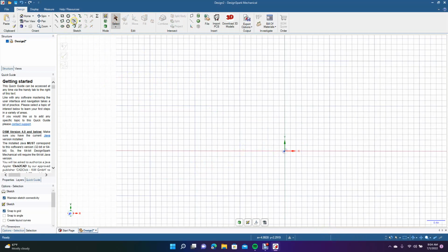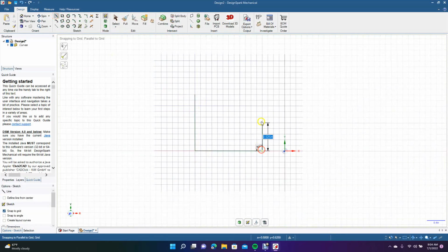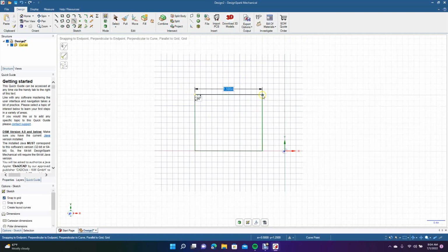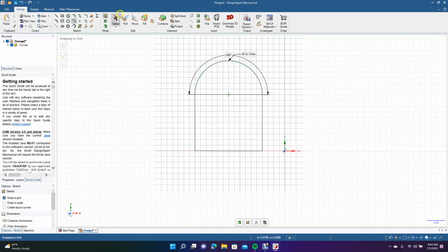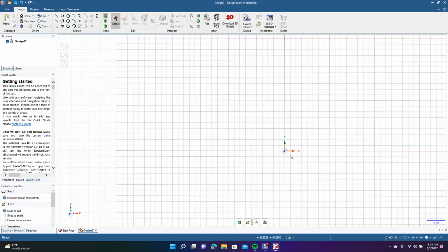Now this is going to be your 3-point arc. The 3-point arc is going to be handy if you have a shape like this and you want to create a round circle there. You'll get your 3-point arc, and then you'll specify from the endpoint, you click there and then you'll click the endpoint there. As long as you have 180, you'll have a completely half round circle. That's going to be that tool there. And we'll delete.